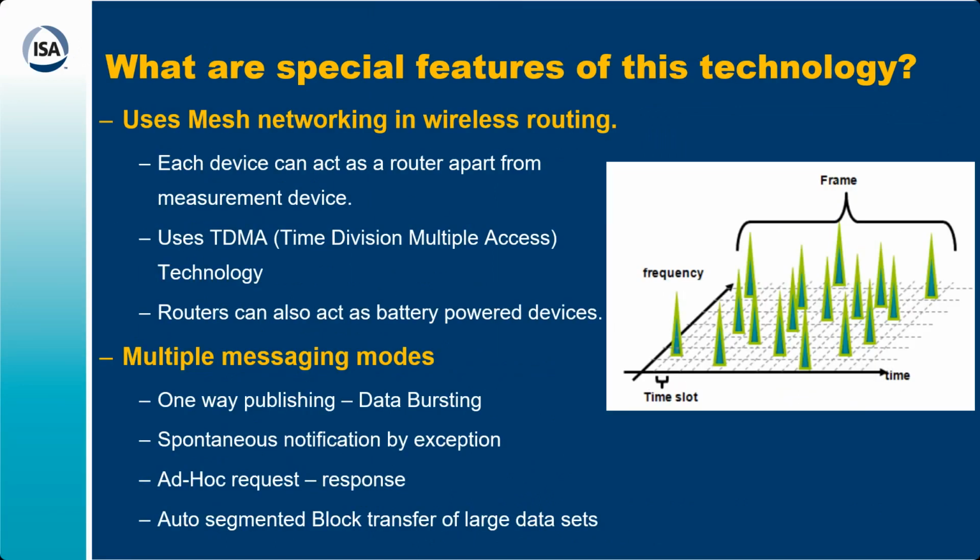So it uses the TDMA technology. What is this TDMA technology? It's time division multiple access. That means all the nodes in the plant are given a fixed time slot, so that no other node shall wake up and talk to each other. Because at one point of time, there's only one node and one network manager in communication,